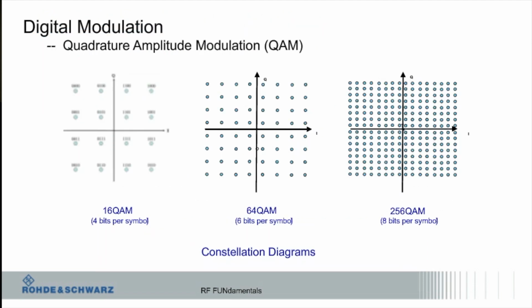So there are other higher levels. We started out at QPSK. The middle 4 dots on the left are QPSK, so that's basically quadrature phase shift. I have 1 level of amplitude and 4 phase states. With 16 QAM, now I have 4 bits. Instead of 1 amplitude level, really 2 because binary is 0, 1, I now have 4 different amplitude levels. So I still have just the quadrature, so there are really 2 phase states, all said and done,